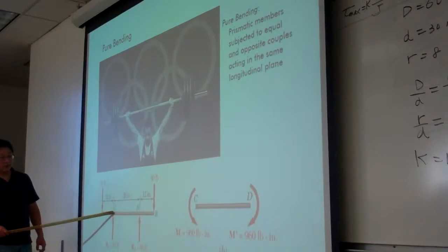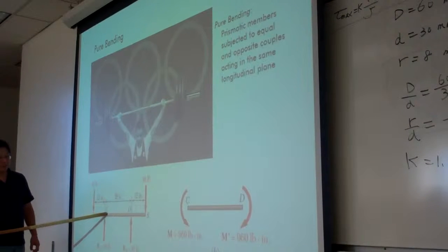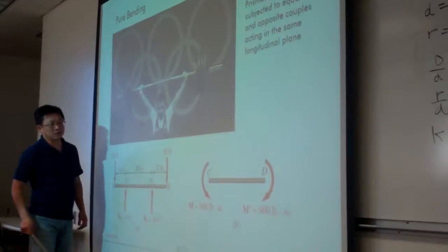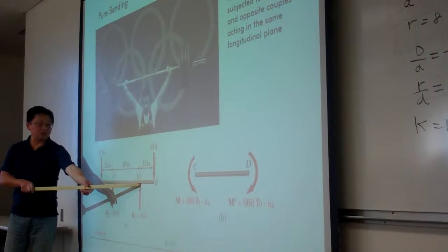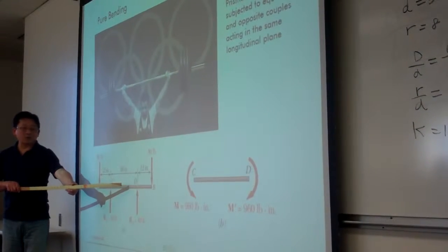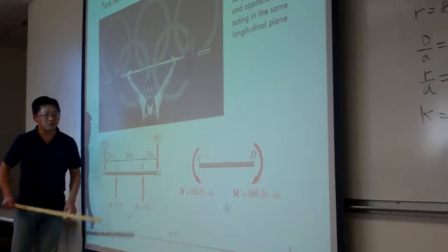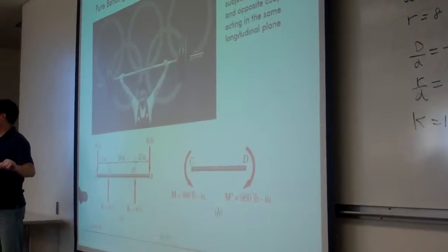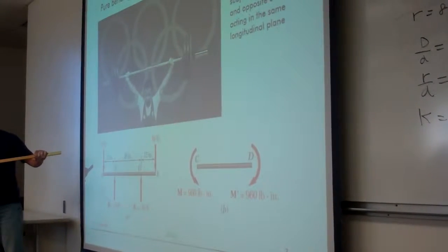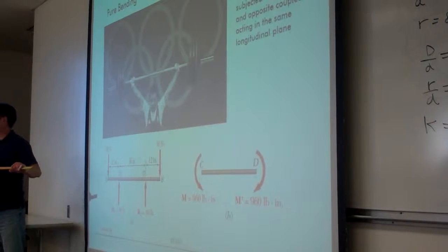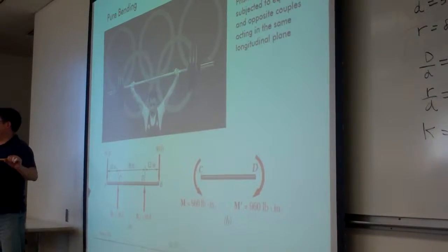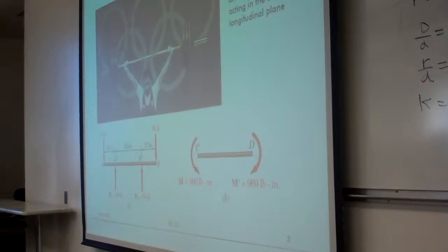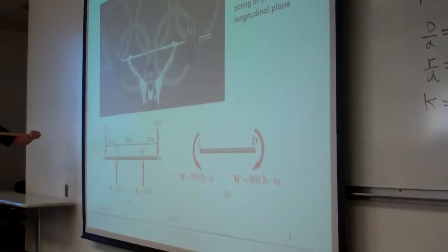But I can tell you at this moment, in portion C, between C and D, the bending reaction at every single cross-section is constant. For this example, it is 960. So in this portion, we say this structure, the segment CD, is under pure bending, and the magnitude is 960 everywhere. This pure bending will give us a simple way to analyze the problem. And once we learn pure bending, we can follow up and extend the techniques to study the bending of non-constant distributions. Okay.